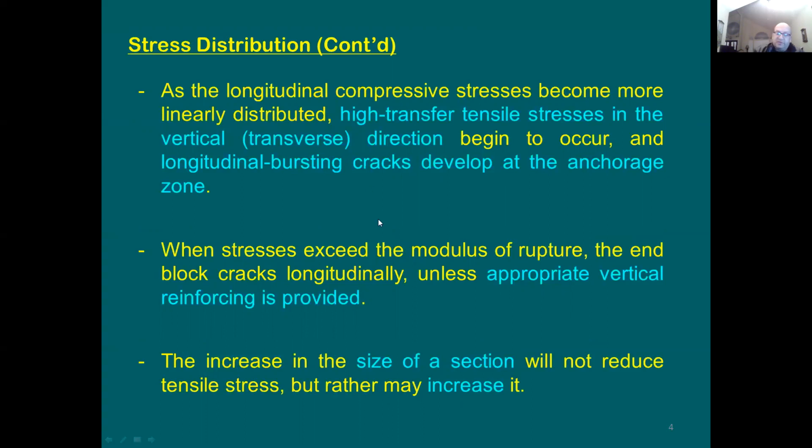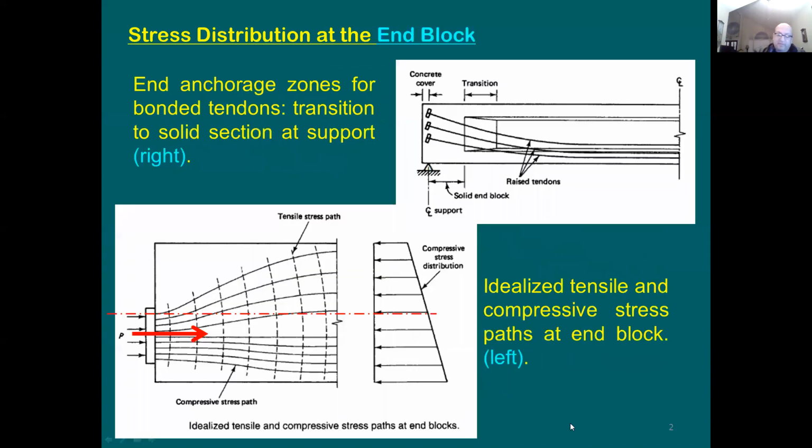More issues here that you need to be careful about. Once you start to put compressive forces, it means that you are developing tensile forces and tensile stresses perpendicular to the direction of the compressive forces. And this is given the vertical and horizontal direction. These tensile forces here, we can call them bursting forces, and you need to resist them by providing enough reinforcing. I'm going to go back here again to our beam.